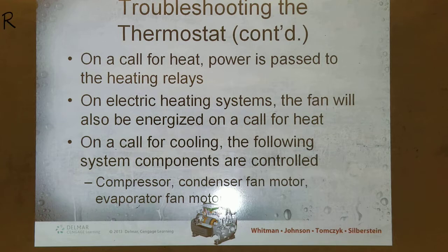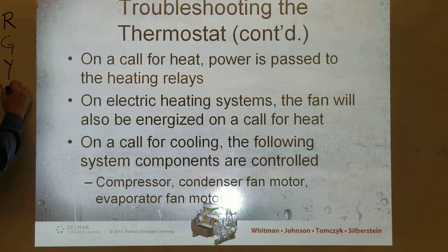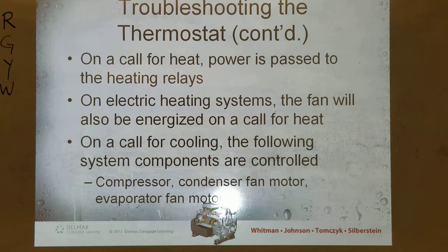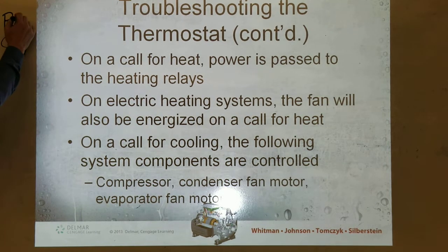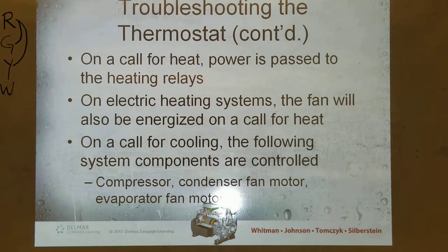Your Y? Or G? We got G, Y, W, and W. So what happens when the thermostat calls for cooling? R and G make, and R and Y make. Okay, I said that backwards? Yes, it confused you. I was like, why is he going to the Y?